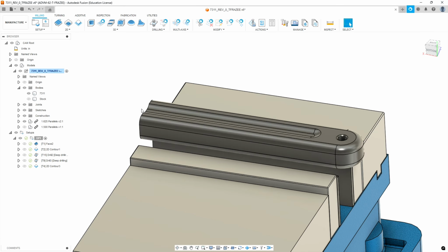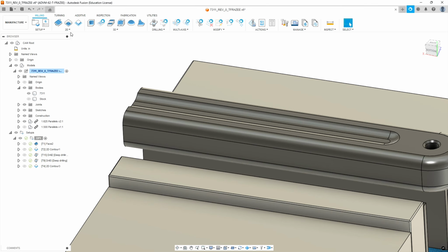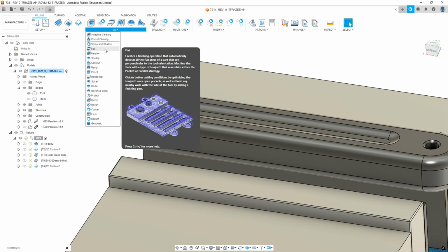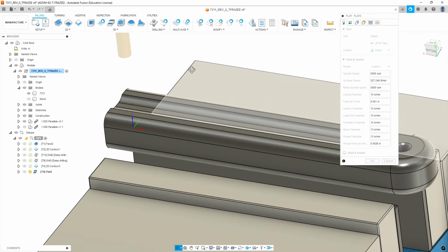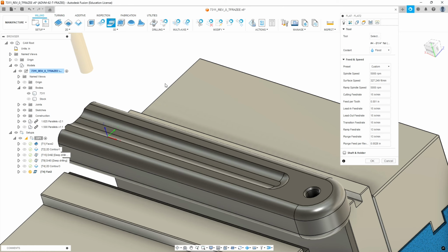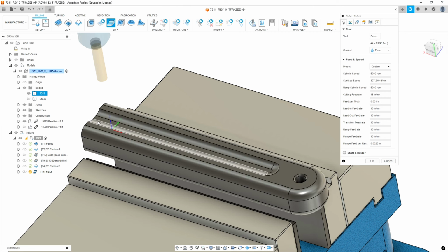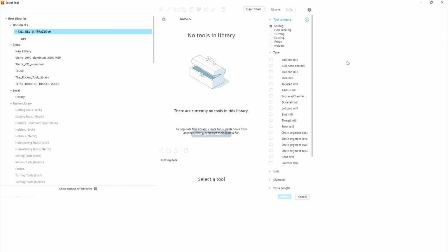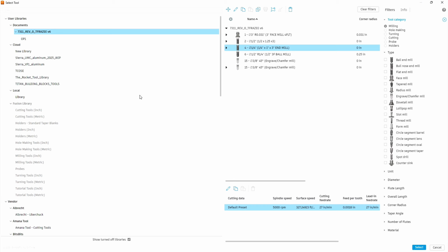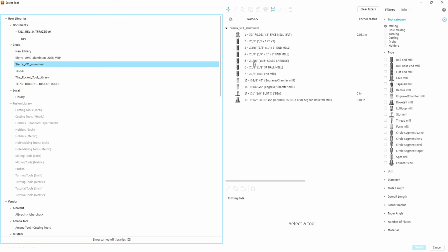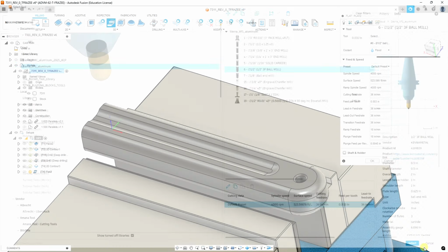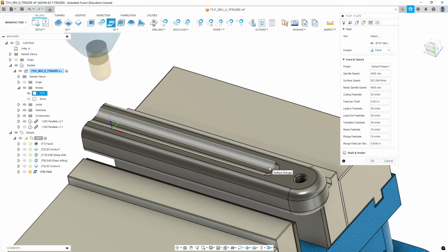Okay, so we're going to start off again. We're going to do the center here, and we're going to use a command under 3D called flat. It's something I rarely ever use for surface machining. It's only in areas where, like this, we've got a flat surface that's too narrow to machine with a flat end mill that we have in our index. So we're going to follow that with a ball cutter. So we're going to cut this with the 1/2 inch ball from our library, which matches the radius on our fillet sizes of the walls.